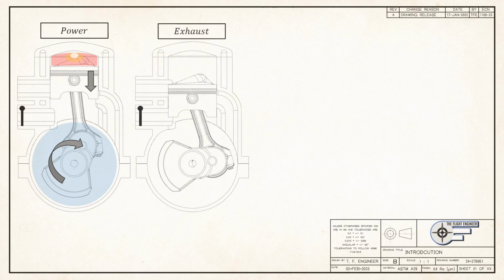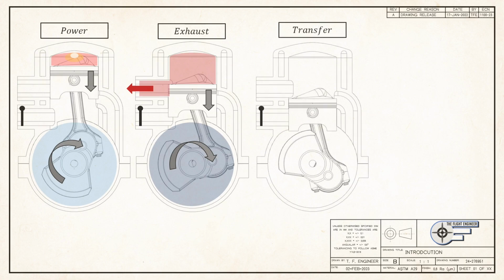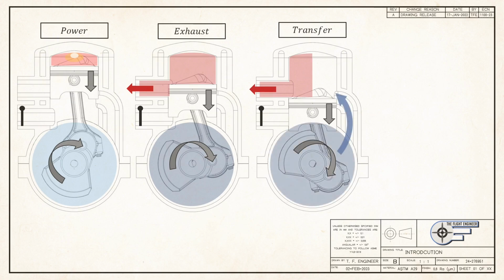When the piston has traveled some way down the cylinder, its crown passes over an exhaust port, allowing hot combustion gases to escape. While this is occurring, the downward movement of the piston is decreasing the volume in the lower crankcase chamber, compressing the charge air inside. Near the bottom of the piston stroke, the transfer port begins to open. Compressed intake charge air from the lower chamber is forced up into the combustion chamber, where it aids in the removal of burnt gases out the exhaust port.